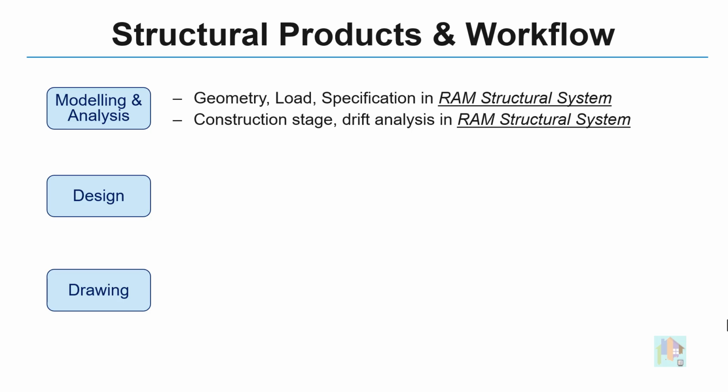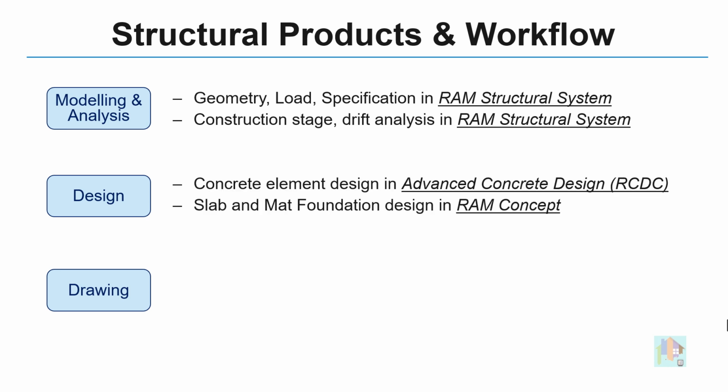To model and design this building, we have used multiple interconnected products. For modeling and analysis, including dynamic, construction stage and drift, we have used RAM Structural System. Advanced Concrete Designer or RCDC is used for concrete element design. For elevated slab and raft foundation design, RAM Concept is used, which is also a finite element software.